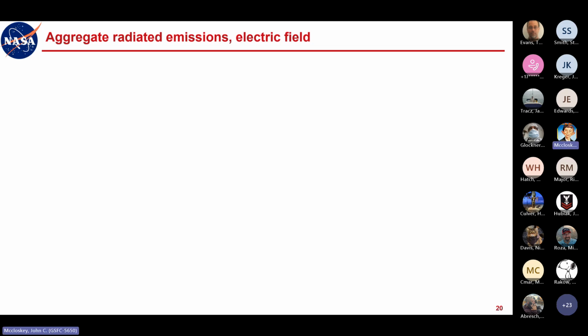I didn't just make that decision unilaterally on RST. I spoke about that with our power group here, and I think it was this very experience that I just related on JWST, where I never got the scope to trigger on a positive going transient for a turnoff, and the worst case negative going transient was a whopping half a volt from a 30 plus amp transient.